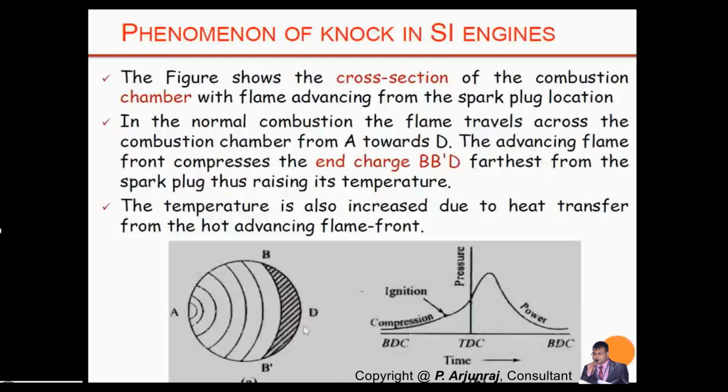So you have the spark plug. When this flame is nearing the location where the spark plug is, it raises the temperature, but it will not auto ignite. Only the temperature will get increased, but that temperature will be lesser than the auto ignition temperature or the self ignition temperature.